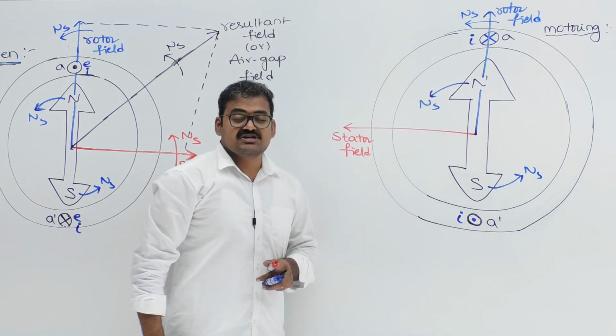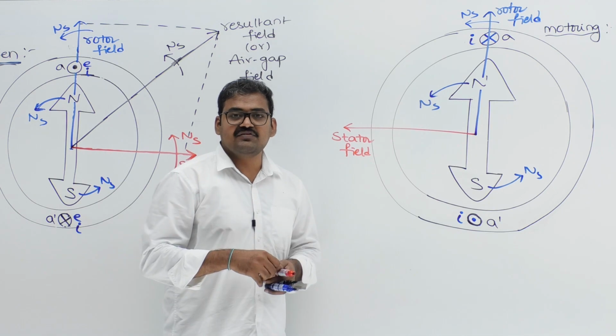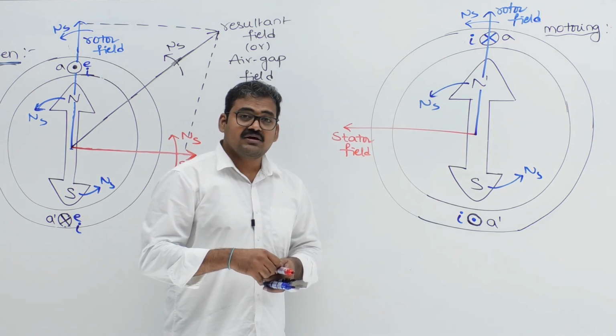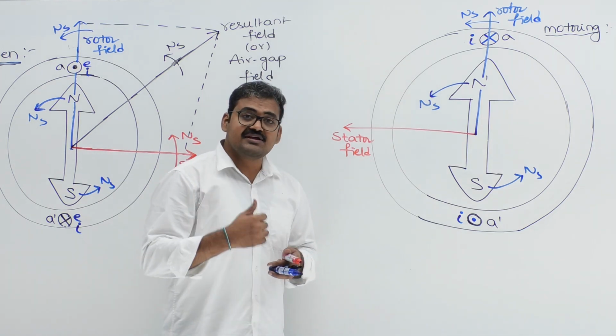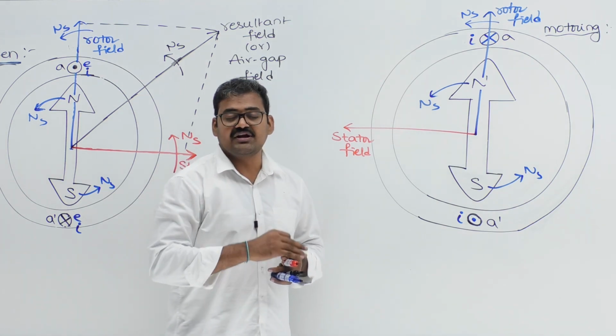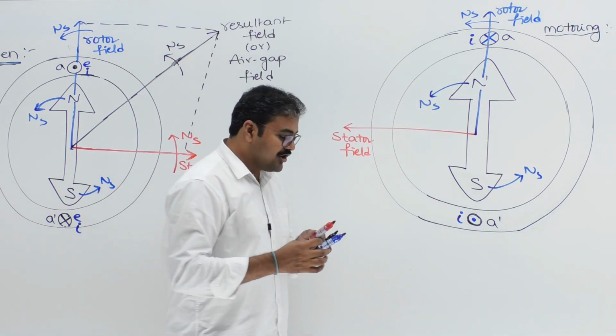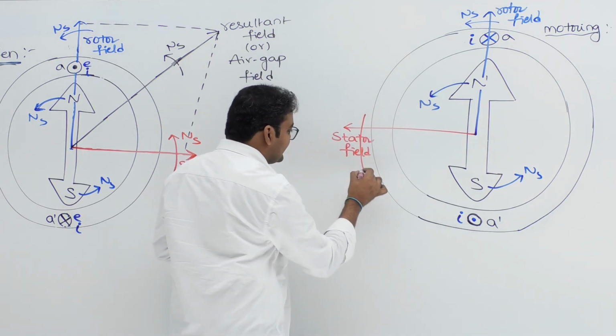Coming to the stator, is the stator field stationary or will it rotate? Definitely the stator field will rotate. Why? Don't say the stator is rotating. The stator field is rotating because the stator is a three-phase balanced distributed winding carrying three-phase balanced AC currents. Therefore, a rotating field is automatically created.